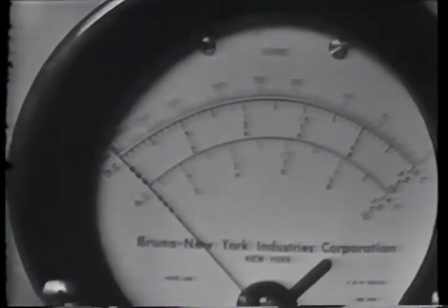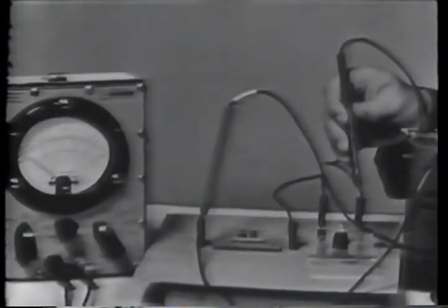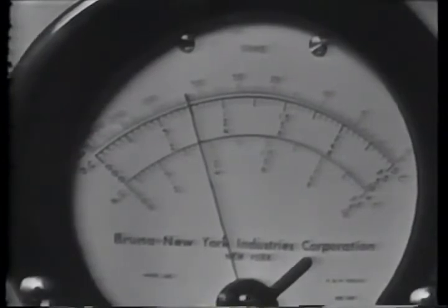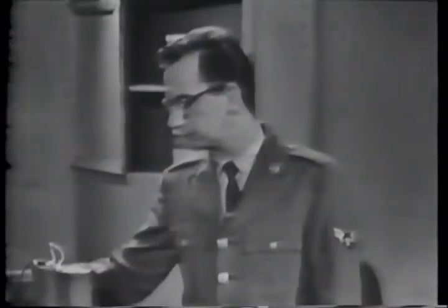This voltage is the same as the applied voltage. Let's check it. As you can see, the values are the same. So, when you connect a voltmeter across a good component in series with an open one, you get 0 volts. On the other hand, when you connect the voltmeter across an open in a series circuit, the voltmeter will read the applied voltage. And now you complete the 2 sentences under number 3 on your response sheet concerning this circuit.